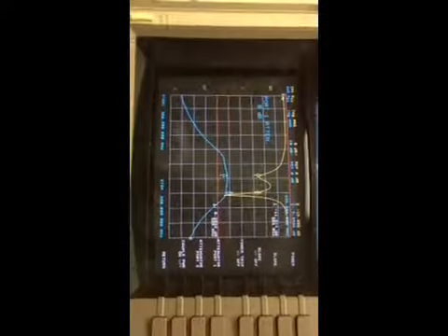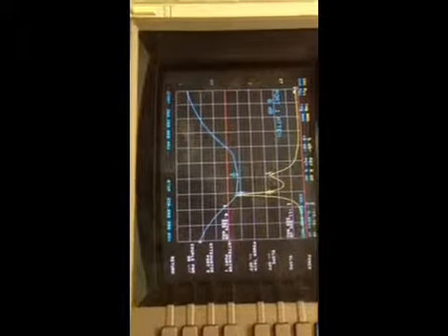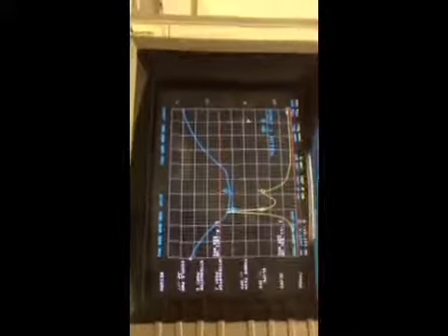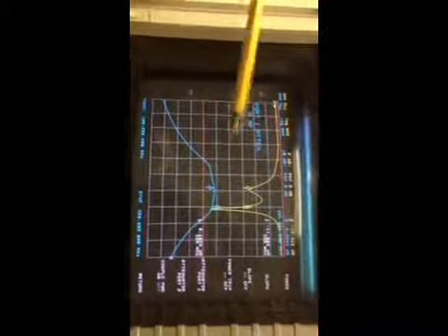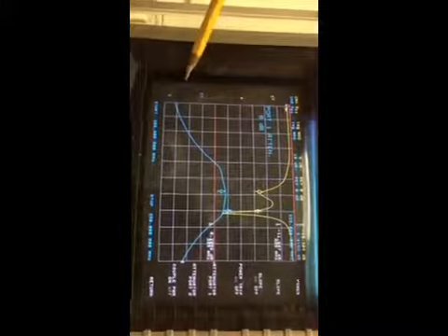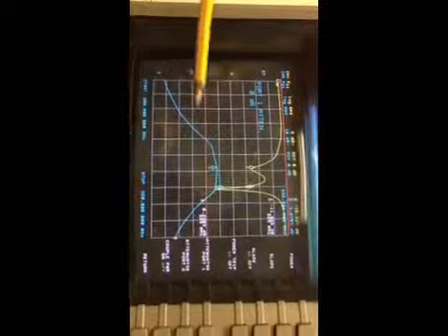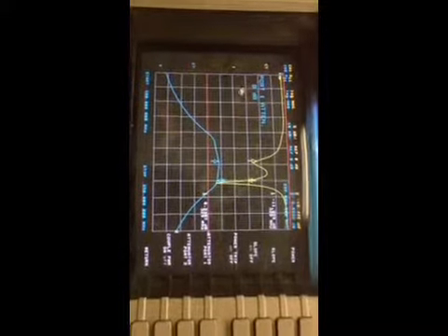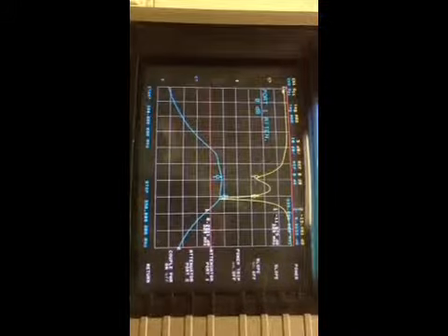much because in our filtering we are more concerned with attenuating the localizer frequencies that are coming in at 108 to 112 megahertz. So as long as we are seeing a significant amount of attenuation, mind you this is starting at 300 megahertz, we're not going to have a problem with having a cross signal or additional intermodulation problems that will cause false readings.